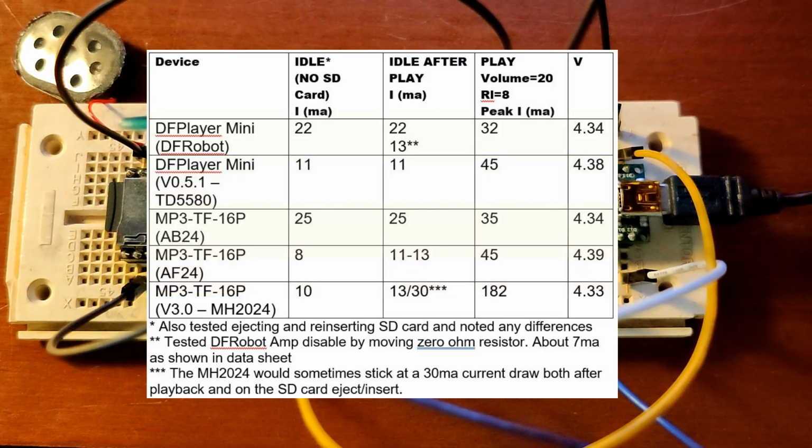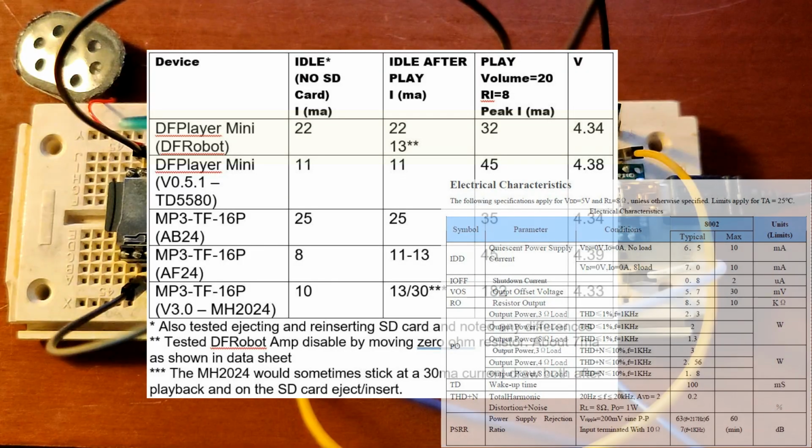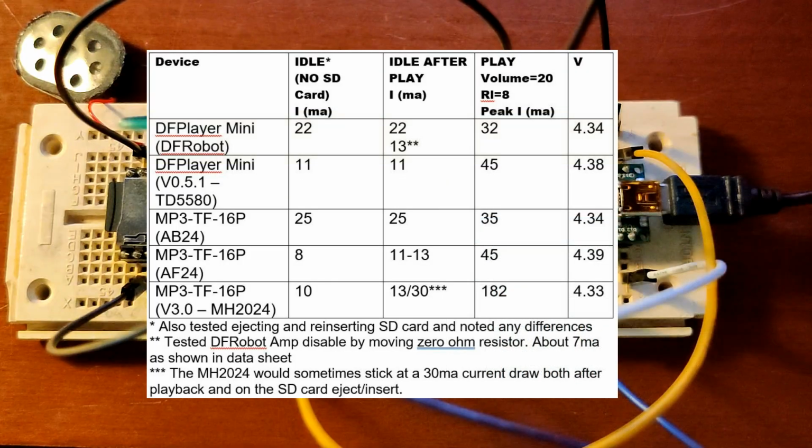The DF robot and the JL AB24 compared well together with a 22 to 25 milliamp current. I did try the amp disable on the DF robot and it reduced the idle current by about 7 to 9 milliamps, which is what the datasheet states for the 8002. I also noticed an audio startup delay in this configuration. Then there's the version 3.0, which was not too bad at idle. It really cranks out the power on play. It has both louder and much higher current, so I suspect that the volume settings are not aligned with the others. One anomaly was that this device would occasionally stick at a 30 milliamp current draw.